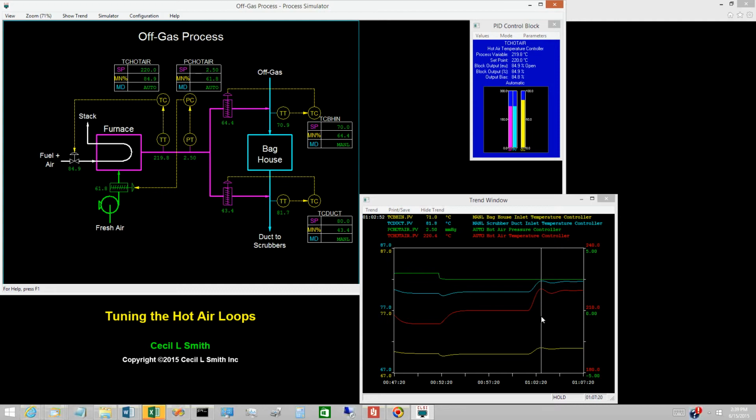The first peak occurs at about 2 minutes 52 seconds. The second peak is only barely visible, but occurs at about 5 minutes 17 seconds. The difference is the period of the response, the value being about 2.5 minutes. The reset time of 1.5 minutes is greater than half the period. The current value for the reset time is reasonable.